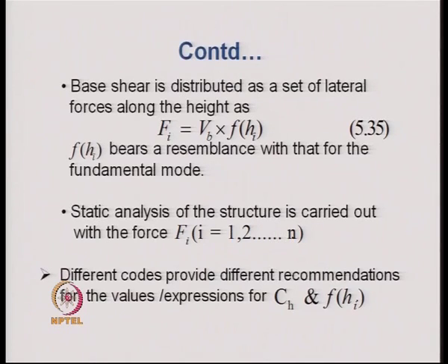They are not the same, but it has a resemblance. Thus, we can see that the loads at different floor levels Fi that we obtain from the total base shear, if they are added together, will finally be equal to Vb, the base shear.